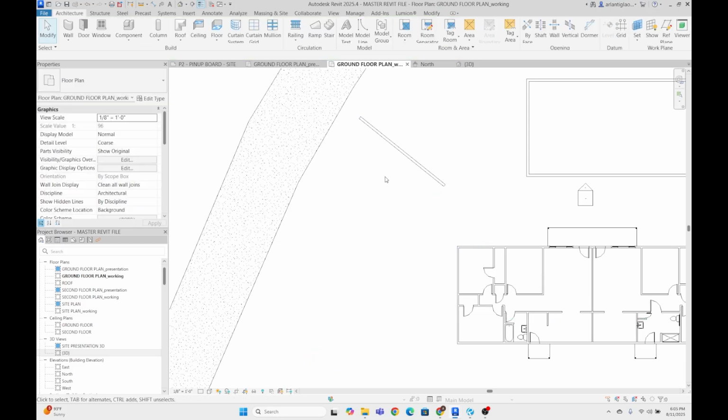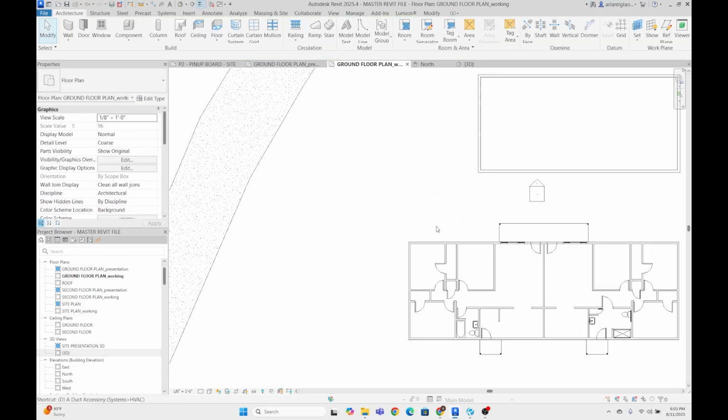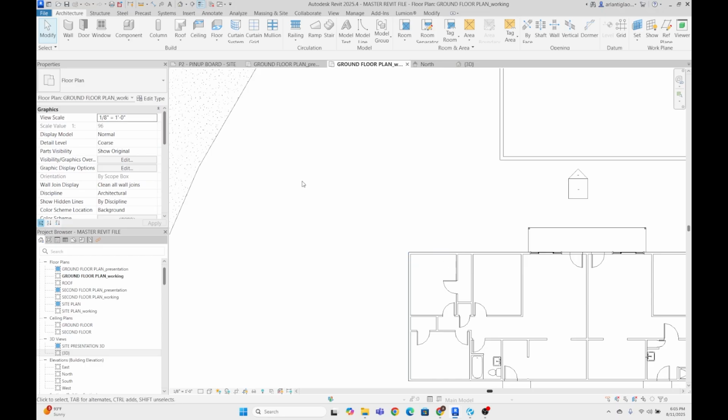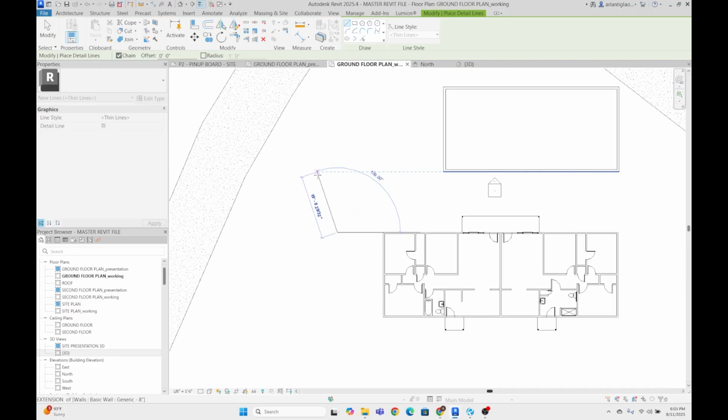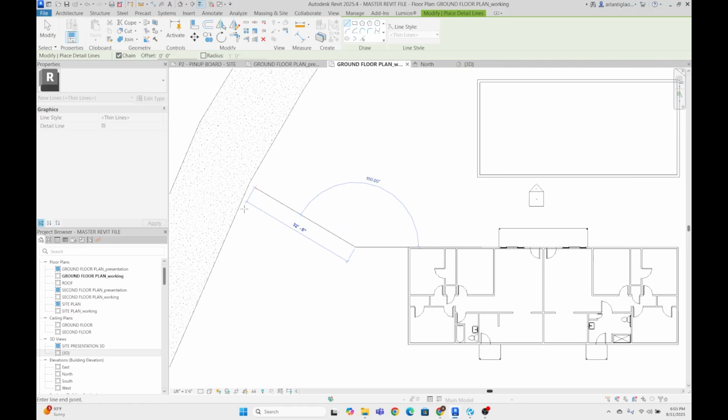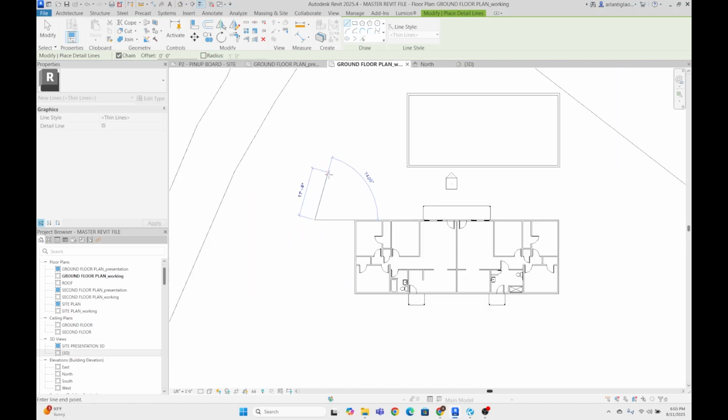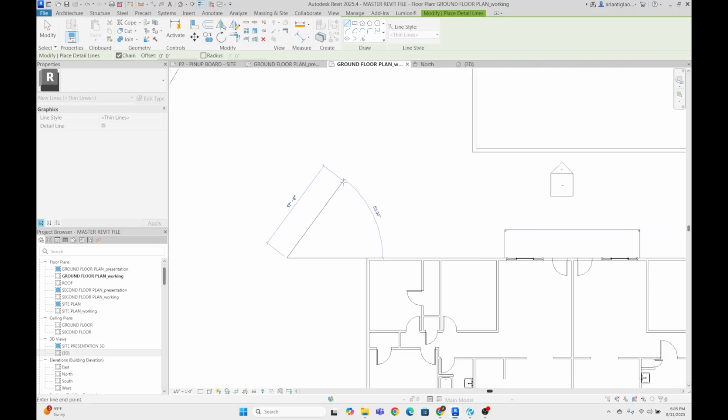When it comes to angled walls, they are a little bit tricky, and a piece of advice is you want to keep your angles whole numbers and somewhat reasonable to work with. So I like to use detail lines to maybe draw a very rough outline of where my walls will go. So if I type DL for a detail line, and then just click off into the space here, and let's say I want my reference walls to be maybe match or be parallel with this road over here, I'll just estimate it to be at about 55 degrees.